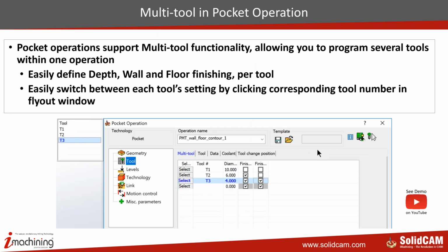We can also now use multi-tools inside pocket milling operations. When you're doing a pocket operation, it now supports the multi-tool function. As a programmer, you can use several tools inside one operation. You can define different tools. You can use a different tool for roughing, a different tool for wall finish, a different tool for floor finish, and individually you can control the